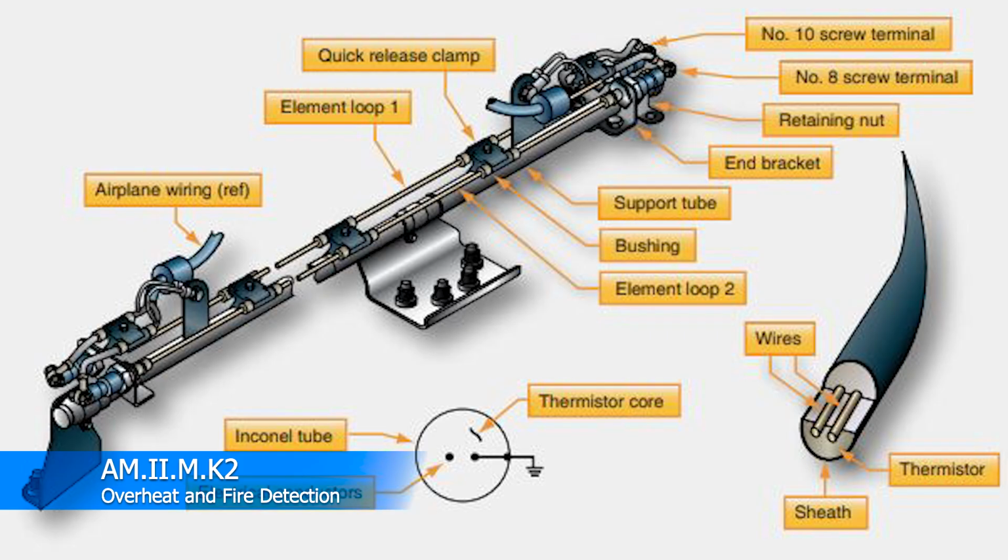Now, the Inconel tubes that shroud the little wire itself, you notice they sit in a little tray or a tube. Anyways, they're perforated stainless steel tubes that are supported by Teflon impregnated asbestos bushings at intervals. The shroud protects the sensor from breakage due to vibration and abrasion against the airplane structure and damage from maintenance activity. So basically, you have those wires inside of that sheath.